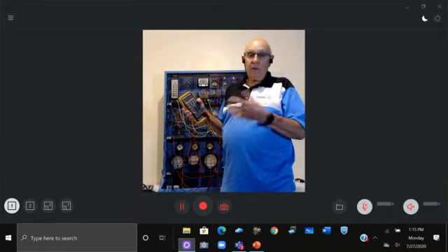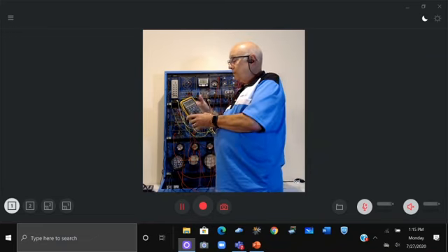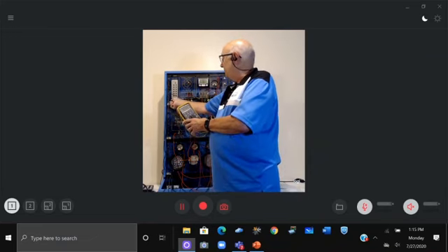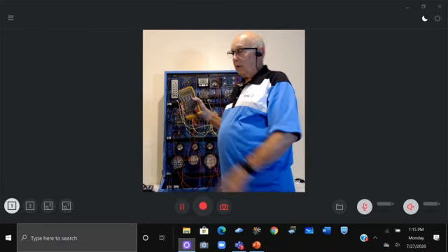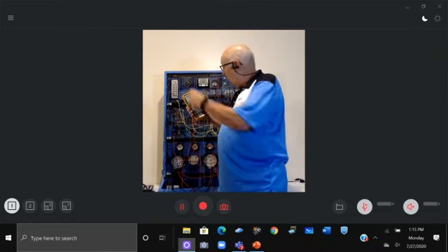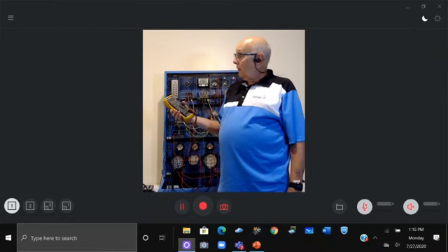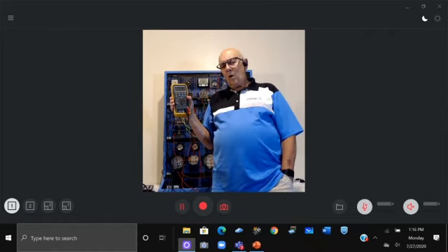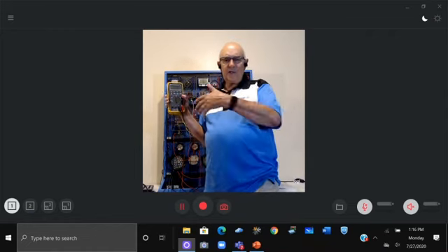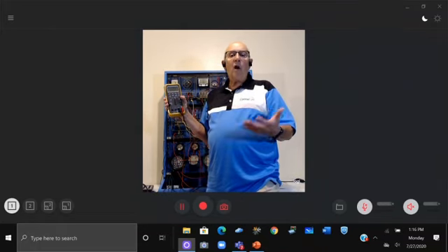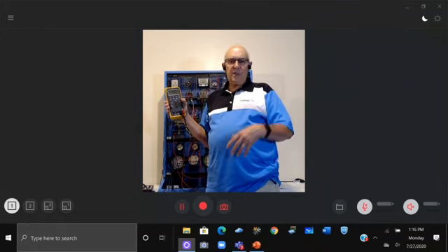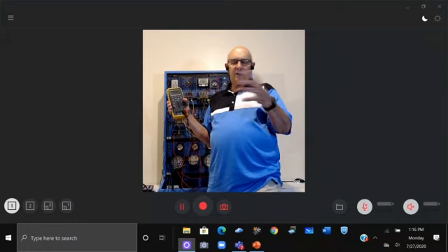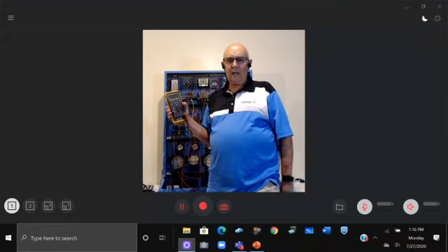Now, real nice, this is a nice part about a trainer. What happens if one of these resistors goes to lunch? I just unplugged one line. I went up to 117.7 ohms. Didn't quite go up to 120, but these resistors on cars, they bought all of the old Radio Shack store resistors when they were going out of business. So they're not a 120 ohm exactly.